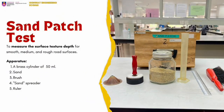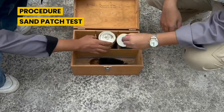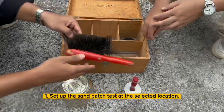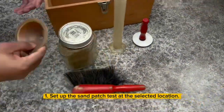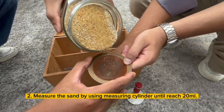In this section, we will be conducting sand patch tests to measure the surface texture depth for smooth, medium and rough road surfaces. The apparatus is as listed below. The procedure for the sand patch test is by setting up the sand patch test at the selected location. Measure the sand using a measuring cylinder until it reaches 20 ml.